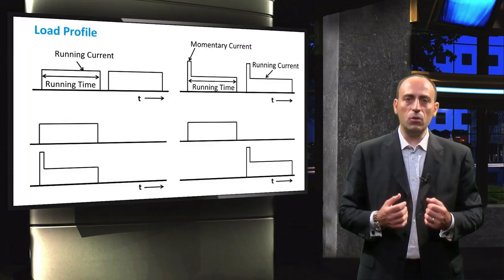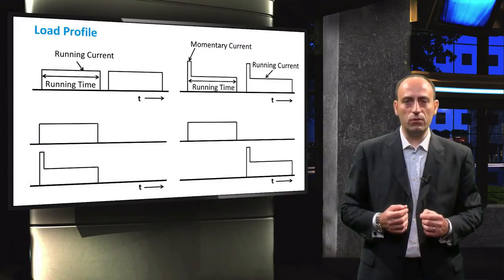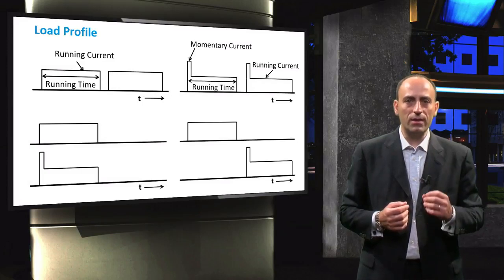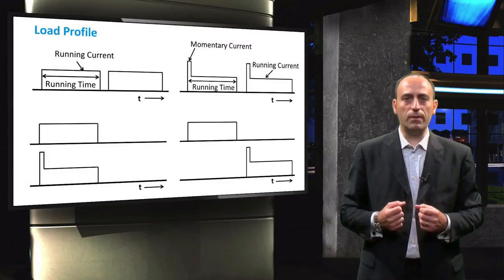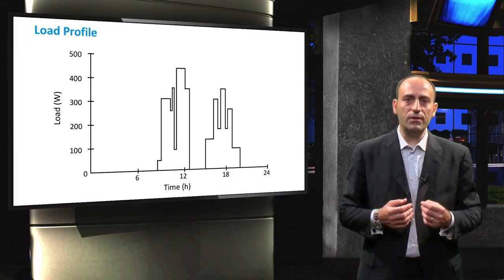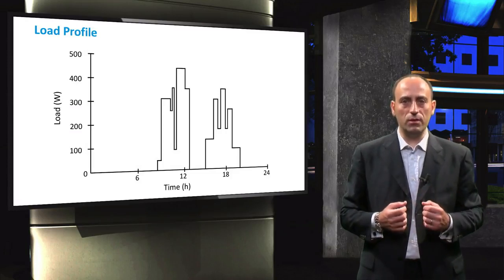By obtaining the load profiles, we can simulate the behavior of the loads that are connected to the PV system. Let's look at another example to clearly understand the purpose of a load profile. This is an approximate load profile of an electric bike charging station, where a certain number of e-bikes are being charged at different times during the day.